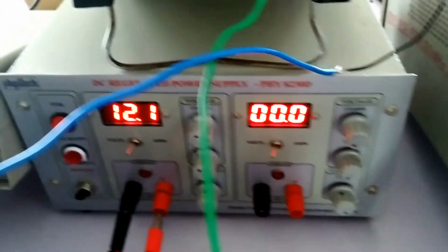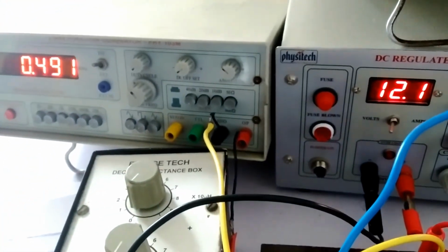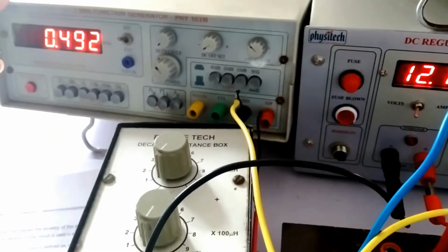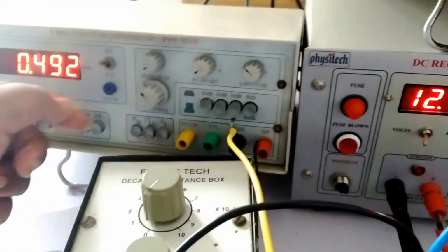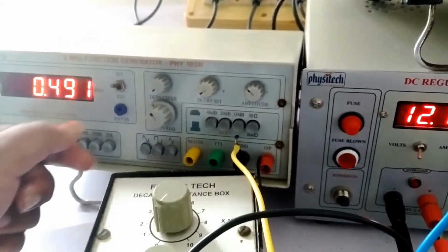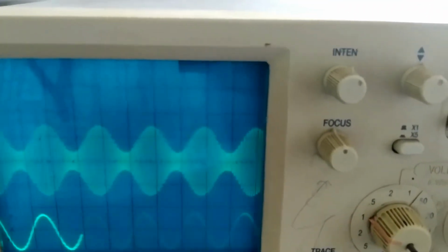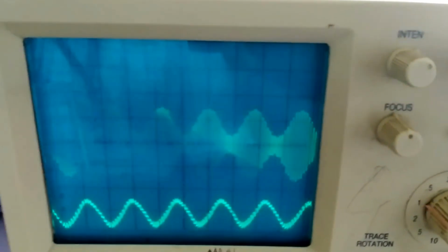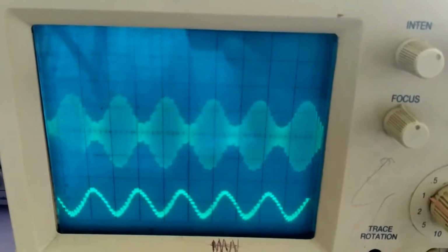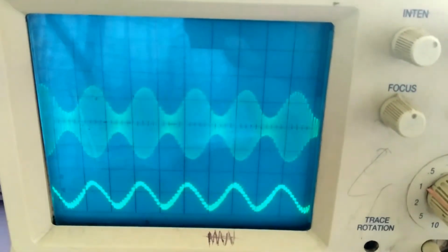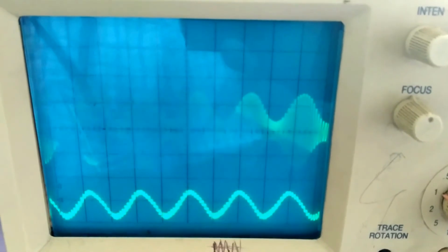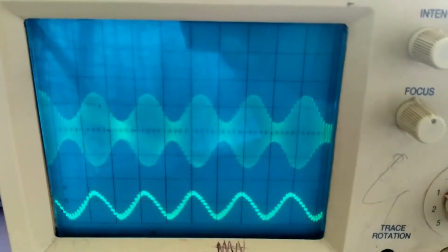Another important aspect is if we change the frequency of the modulating signal, the impact on the modulated waveform. Here set it as 500 Hz. If I change the frequency, there is no impact on the modulated waveform, because in an AM wave, variation depends on the amplitude only. Here I am varying the frequency, and there is no change in the amplitude of the modulated signal. Even in this case, you can take different possibilities. Set the frequency as 500 Hz, 600 Hz, and measure A maximum, A minimum. In either case, you will get the same values.